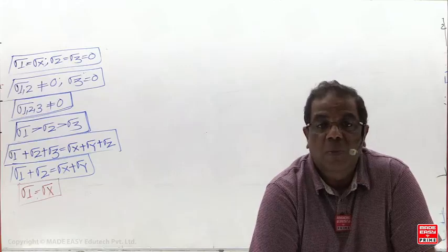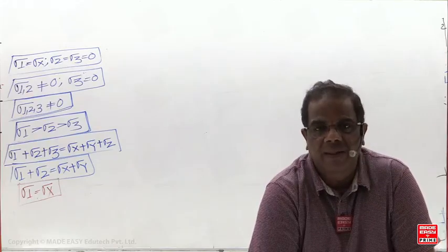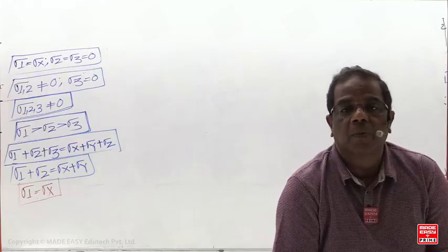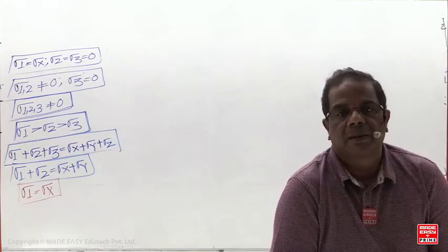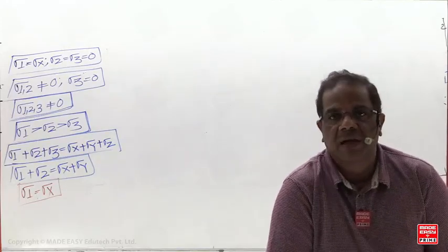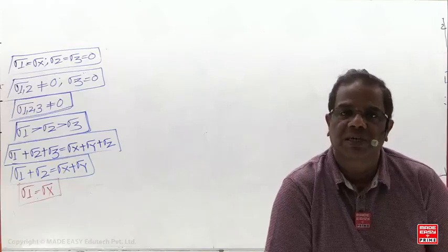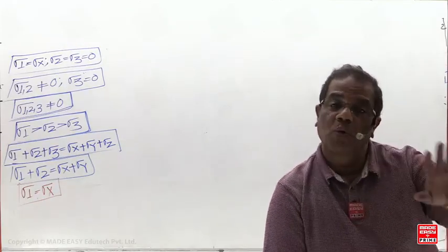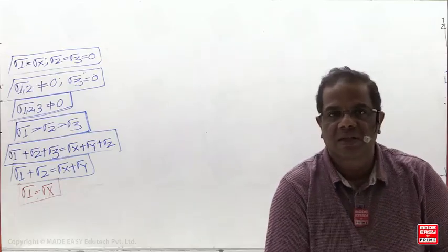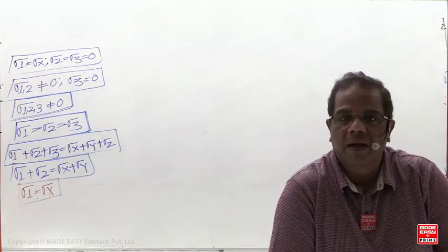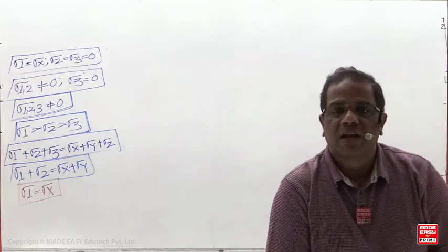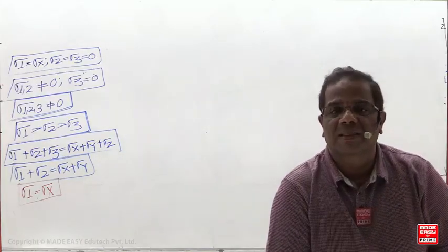Then tau max planes are also known as planes of pure shear stress. What is the meaning of pure shear stress? Only shear stress will be there. On principal plane, you are getting only normal stress, shear stress 0. But on tau max plane, we get only shear stress only when sigma x plus sigma y is 0.